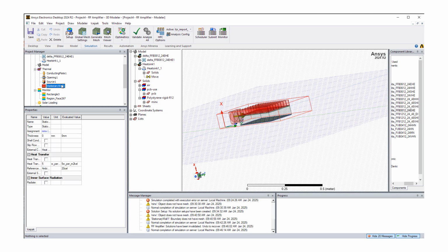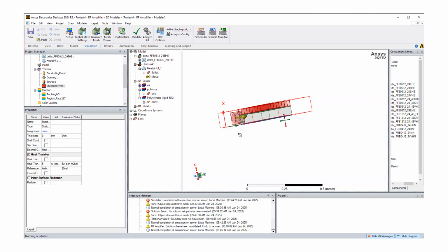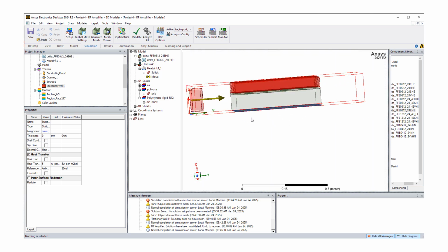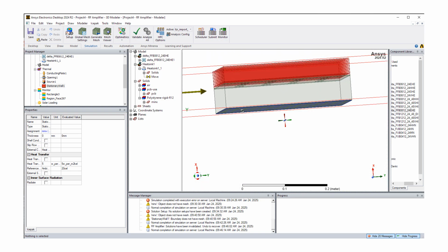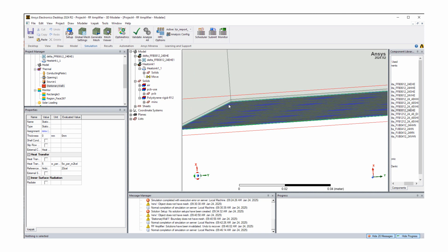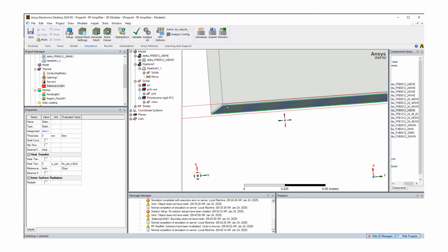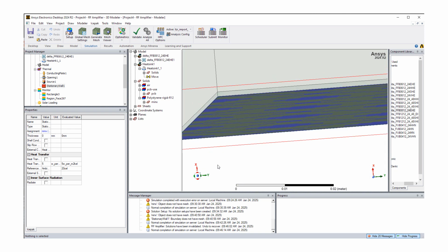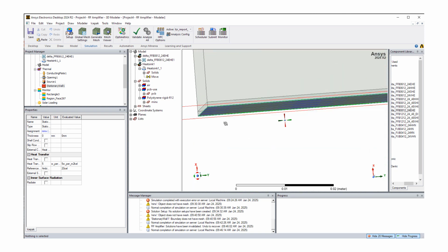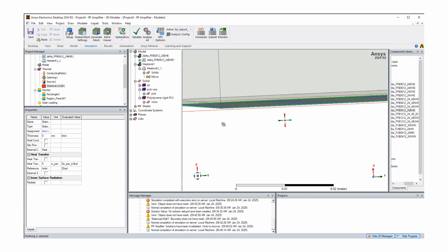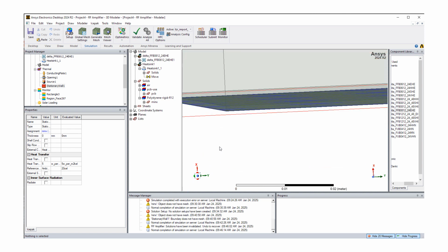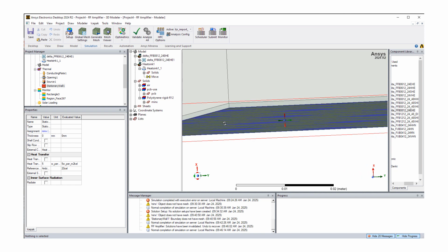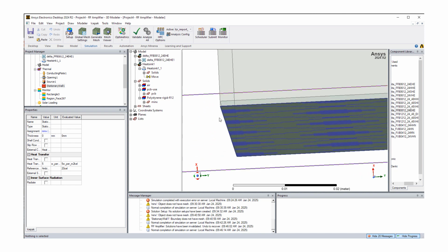This essentially has to do with our thin wall here, because of its thickness, we had defined this as a surface on the back side. So this could be a problem. Maybe we do want to change this type of boundary condition.